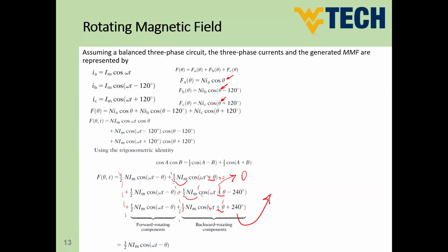If the magnetic field is not in rotating form, you will have a problem. You cannot rotate the machine. There is a machine called the 2-phase machine, and another called the single-phase machine. These machines need something to make the motor start. They cannot start automatically. But a 3-phase machine can start automatically because it has a rotating magnetic field.